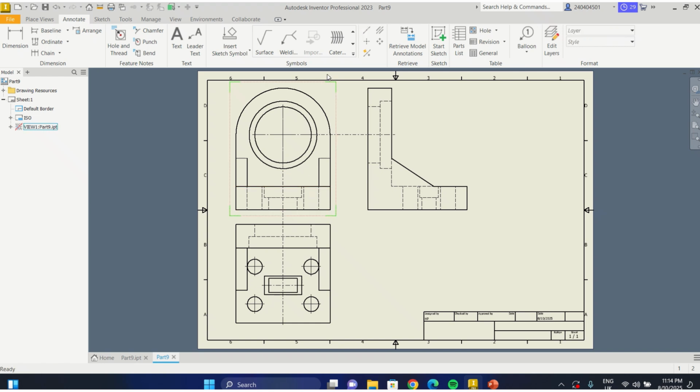Or alternatively, so that you will not be drawing a line that is not straight, join these two centers together, and then from here, draw your line. So that produces your center line. You should be able to draw it out. So that's the center line. You can do likewise for this one too. First of all, join the two centers together.